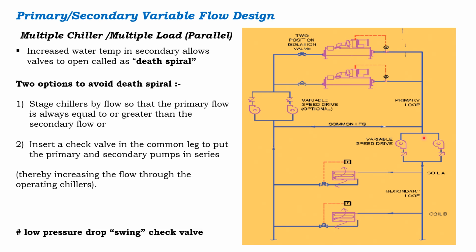It is advisable, as I mentioned, to provide a low pressure drop swing check valve over here in such conditions.